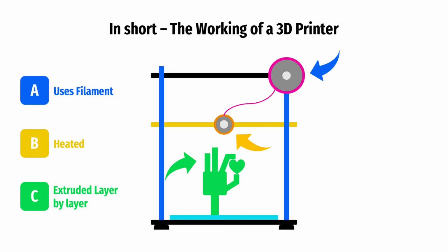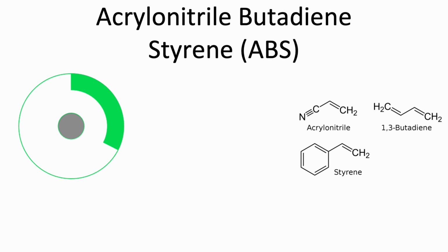Acrylonitrile Butadiene Styrene, or more commonly known as ABS, is the type of filament that most people go for after PLA. However, is it even worth the popularity? ABS was originally one of the earliest filaments and the go-to for 3D printing. However, as PLA came along, it overthrew ABS as the most popular filament. As PETG is also further developing, ABS is soon going to lose popularity. But why? This is because ABS is extremely difficult to print.